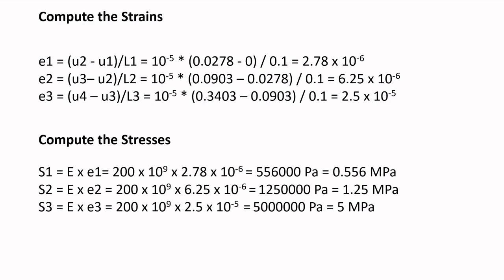So 0.556 megapascals, and similarly the stress in the second element is 1250000 pascals, that is 1.25 megapascals, and stress in the third element S3 is 5 megapascals. So this is how you can compute the stresses using the finite element analysis approach using MATLAB.